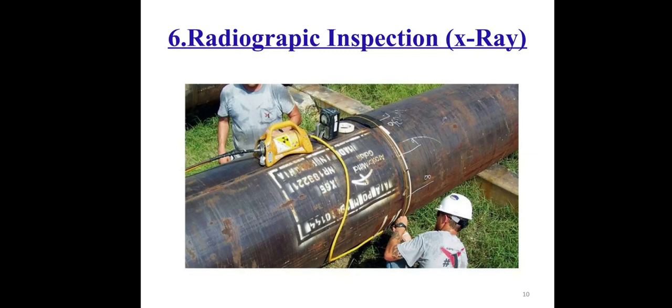Application of radiography inspection. Detection of internal discontinuities such as shrinkage, cracks and porosity in castings. Verification of integrity of internal components. Determination of the quality of welded sections and pipes. Identification of the extent of corrosion. Inspection of a variety of non-metallic materials. Locating discontinuities in fabricated structures, assemblies, etc.